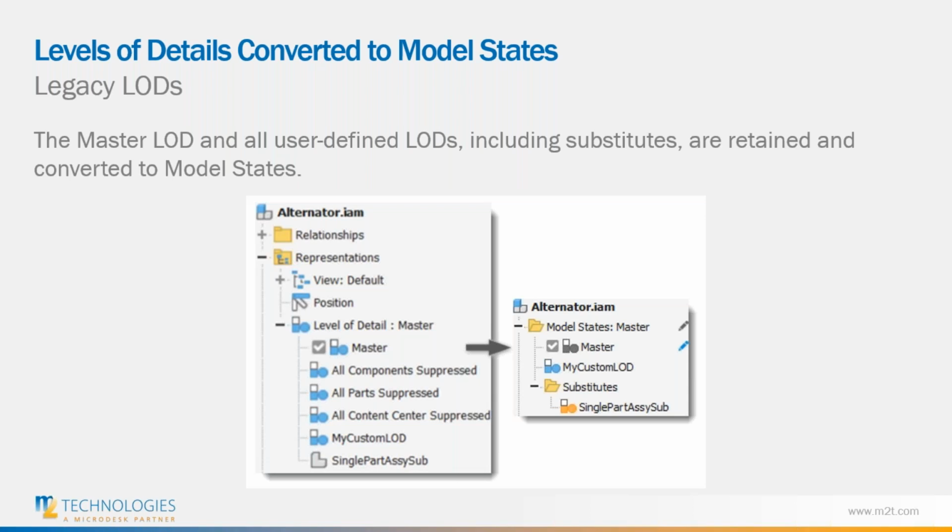So the great thing is, the master LODs, the user-defined LODs that maybe you've created, all will come straight over and become model states. So there's nothing really you have to do. Just basically LOD is going to be removed from your browser in 2022. And now you'll look under model states and anything that you've done is still there. So you didn't lose anything that you did, okay?